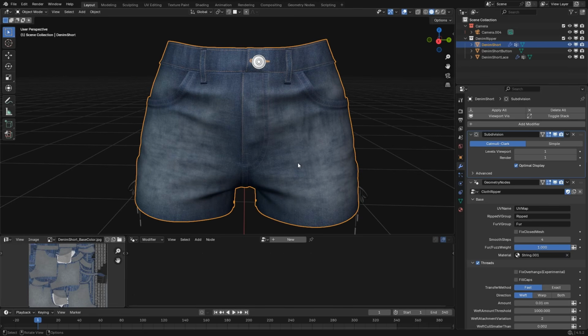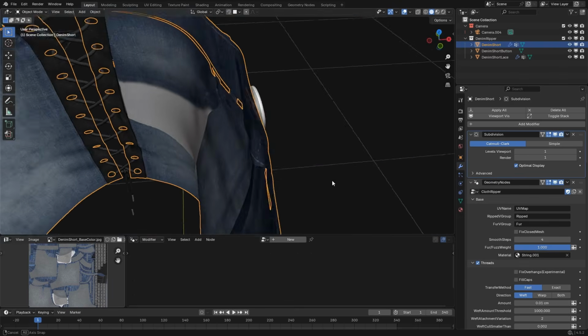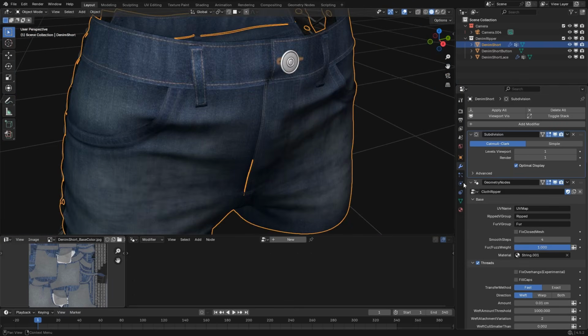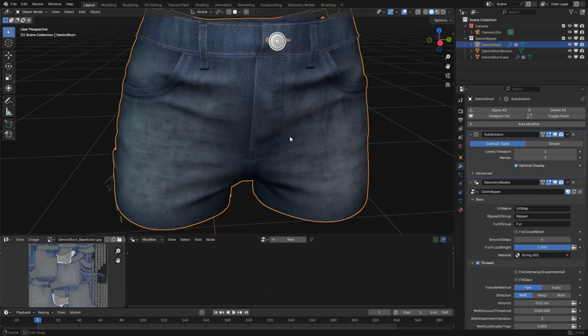If your mesh is closed, for instance, if it's a watertight mesh like a cube or a monkey, you could use Fix Closed Mesh, and this will fix it. The reason I told you not to use Solidify is exactly because of this and the fact that it's much harder to paint vertex groups on a solidified mesh rather than a one-sided mesh.